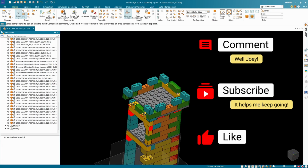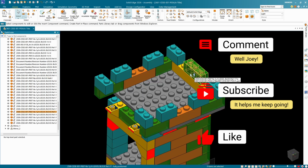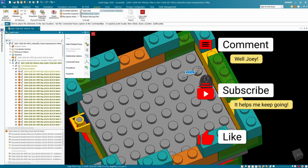So it kind of looked like a lot of work, but it wasn't really that bad. So now we have our part moved to the correct position, and the parts above it are all fully constrained and in the right position too. That wasn't too bad. It was kind of a little bit old school, so there are other ways of doing that. So in our next video, we're going to look at how we could have done this move using the steering wheel in Solid Edge.